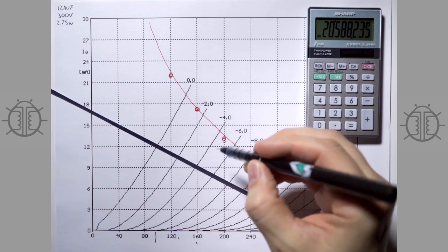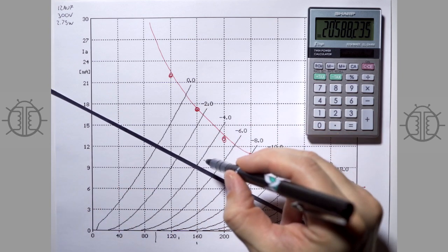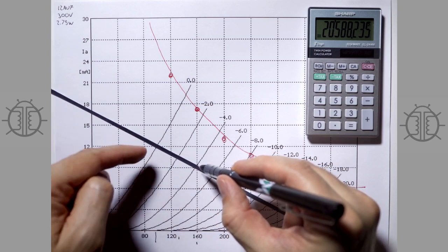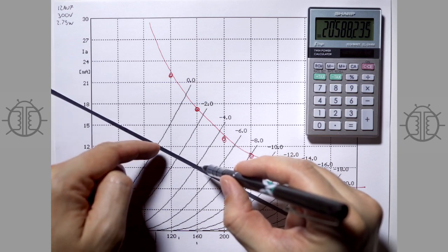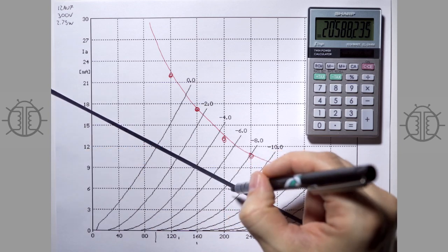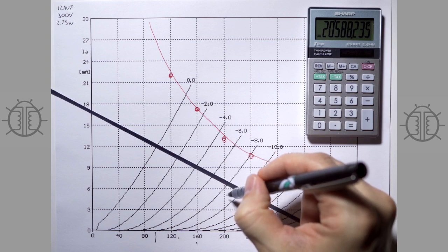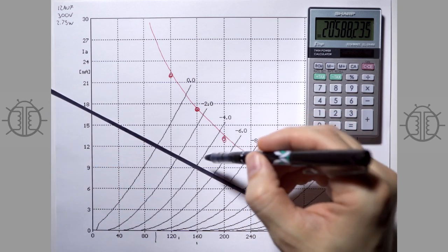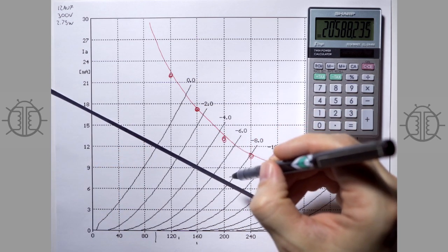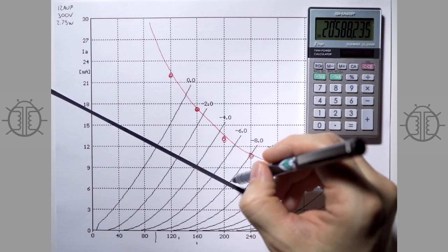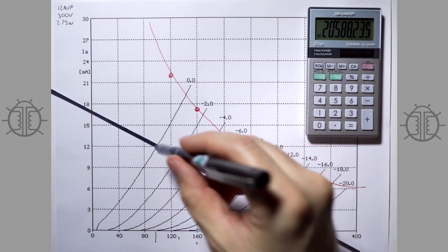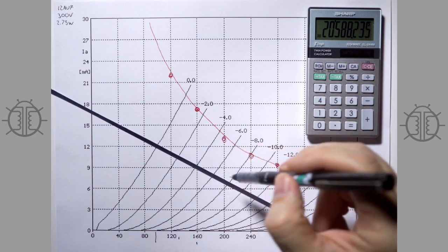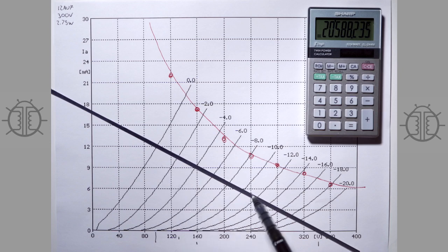And so you could come up here, for instance, and set your operating point at negative 4 volts, and then you could swing from 160 down to 90 there, and you could swing up to 210 or something up here. And so you can see now that the output swing is going to be greater, but you can also see that this is the second order distortion coming in, where one side of the waveform doesn't swing quite as far as the other in voltage. And so you have a trade-off here between sort of the maximum output swing you can swing.